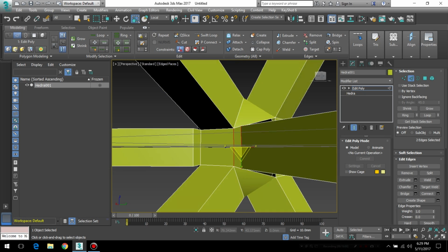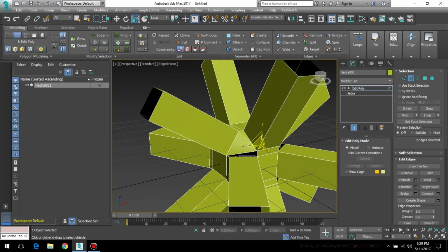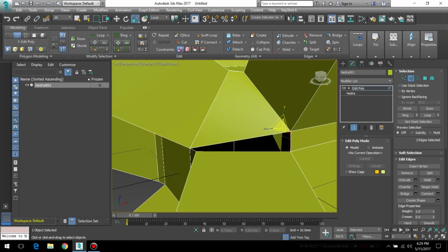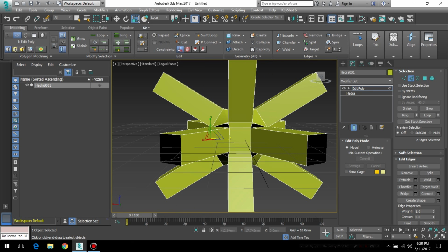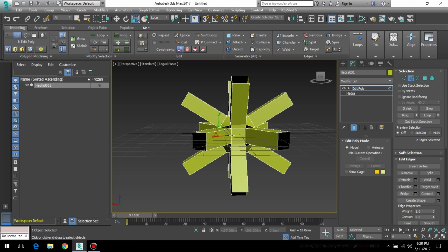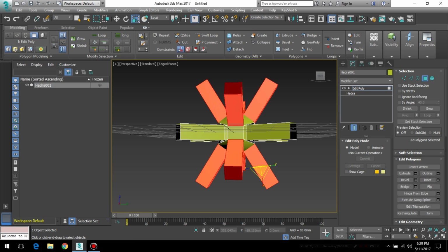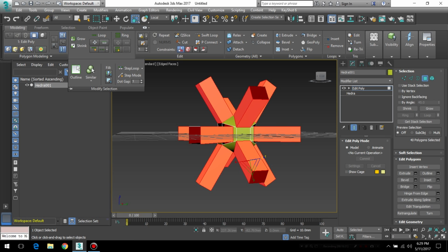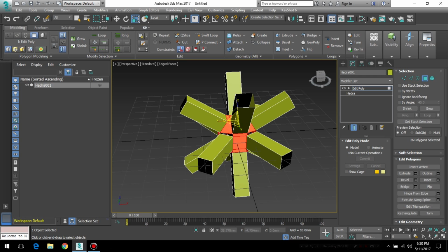Okay. So now all that's left are these quadrilateral holes. So these can all be selected at once and closed with the cap tool. The way we'll do that is just to go into polygon mode, and I'll select all of these rectangular legs here, using any means necessary just to select those. All right, and then I'll press Control I to invert that selection.